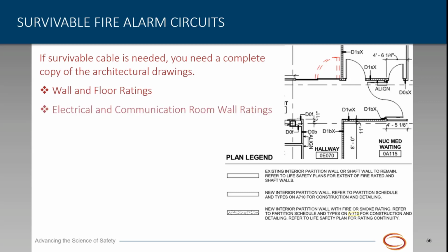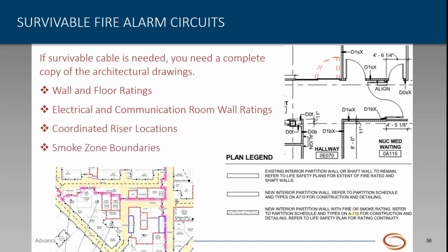Now, you also need the smoke zone boundary drawings, especially in healthcare occupancies. Based on the boundary locations and electrical room locations, the locations for survivable cable runs can be identified prior to bidding in order to properly capture installation costs.